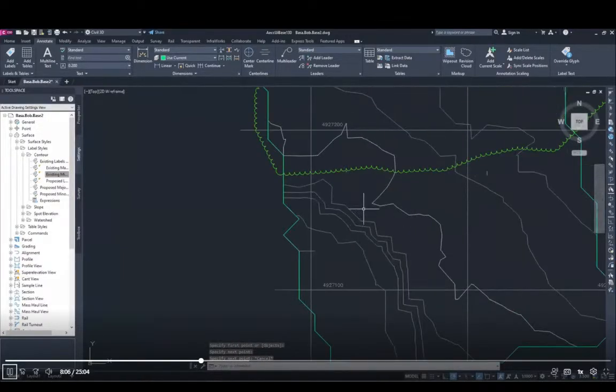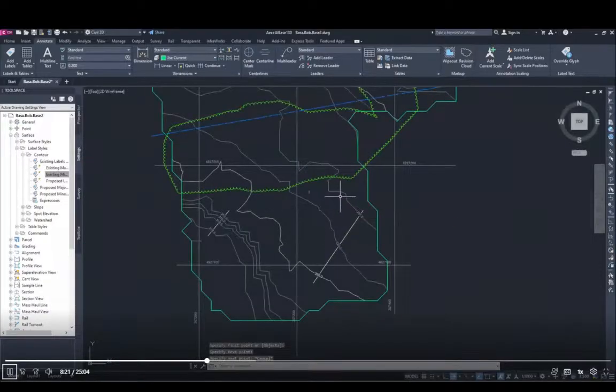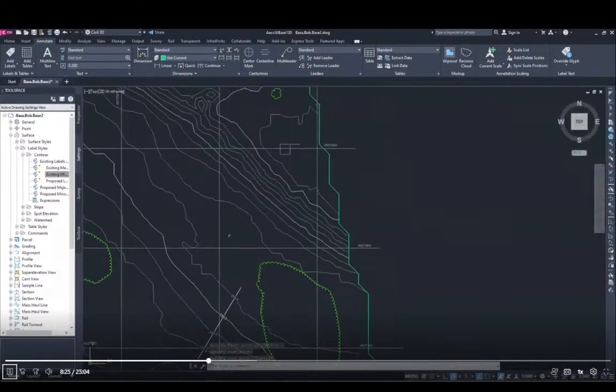Let's zoom in here. How are we going to do this now? Let's do it like, I hit Enter. All right, just labeling the diagram. Let's move to the right. Maybe I'll go across here like this. Escape. Let's find some good spots to do. That's already done there. So I'm going to come up here. Maybe I'll go across here once. Enter. Remember, Enter is always the last command that you did in AutoCAD. So that's why I'm hitting Enter here.